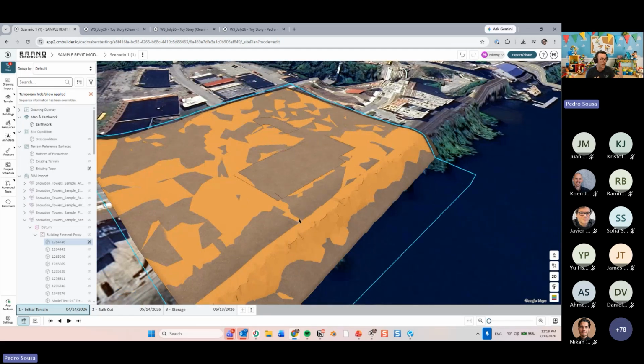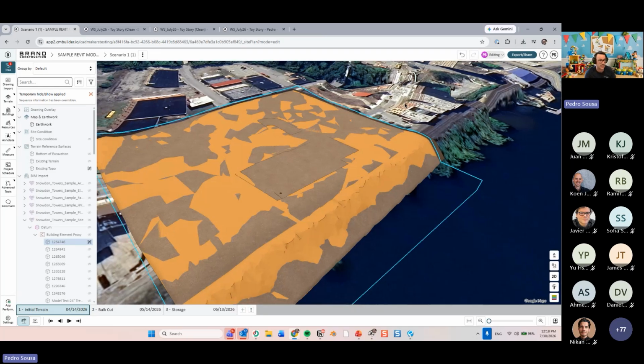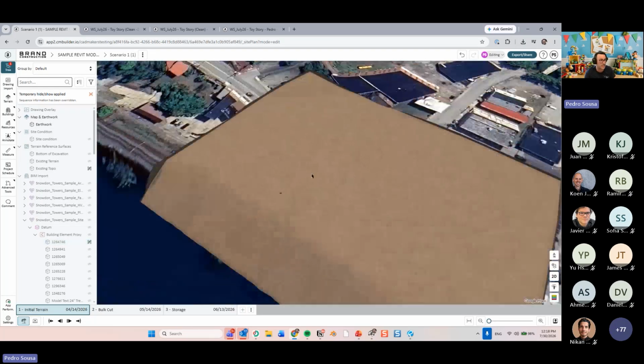Okay. So this is a way for you to recreate the existing topography. I use the model right now, but you could use contour line drawings, or drawings that show control points of topography and whatnot. If you don't have any of these things but you have the model, you could trace the area around your model to make sure the terrain will match that model properly. This is something you can use many references for.